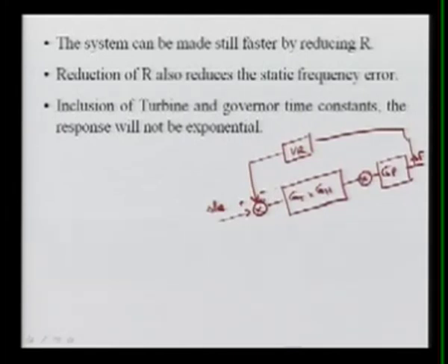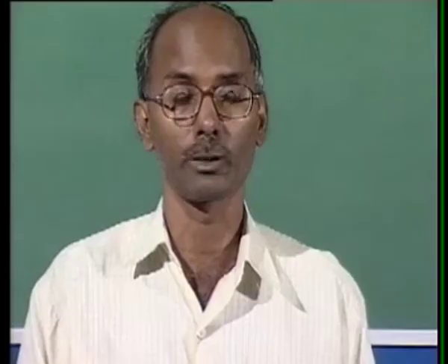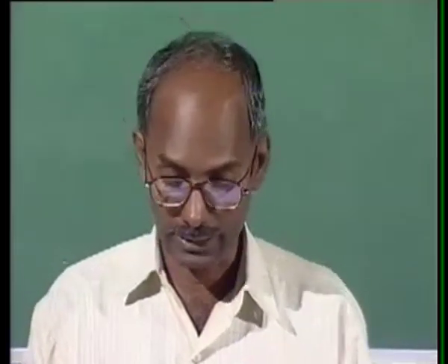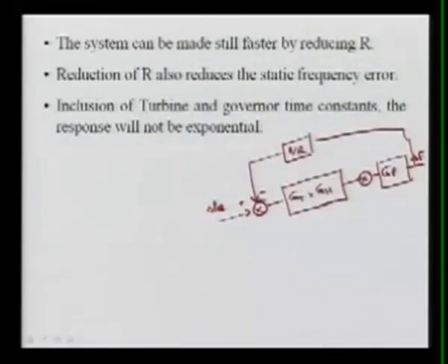It is possible if we do not have this feedback loop, and that feedback loop is provided by the governor here, that is R, the drooping characteristic. So this value is only trying to reduce and speed up the change in the frequency, that is, the regulation governor will take action. If it is not there, then the time constant of the whole system will be the same, just 20 seconds. Here they are very fast and they will die out.